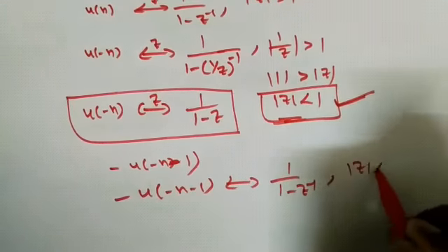So we will get one more pole, 1 minus j, in this z plane. That is the meaning of this conjugation, right? If x of n is real, x conjugate of z conjugate is also equal to x of z. That means it will have complex conjugate poles. If 1 plus j is there, then 1 minus j will also be there in the z plane. Right? This is the real part.